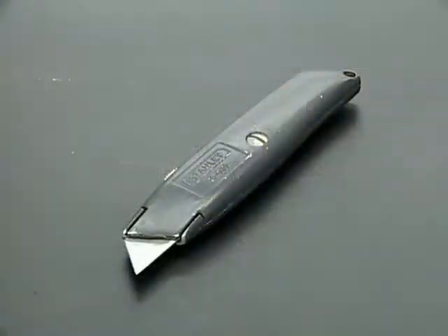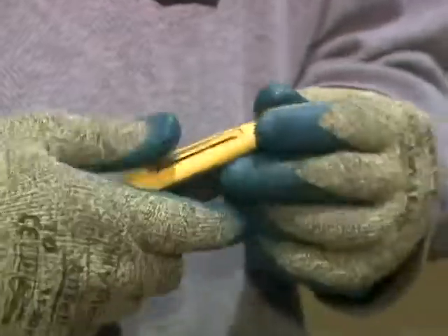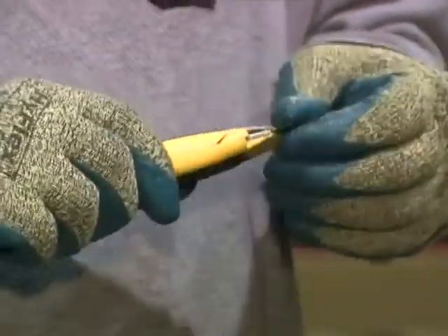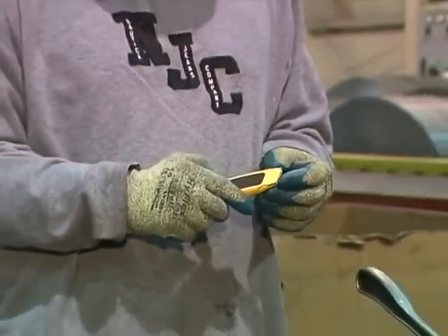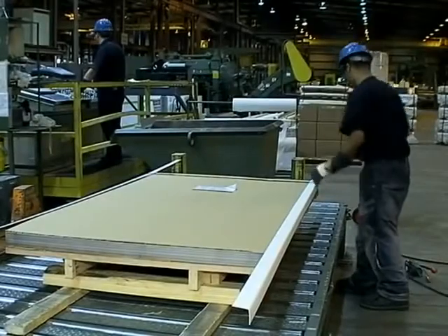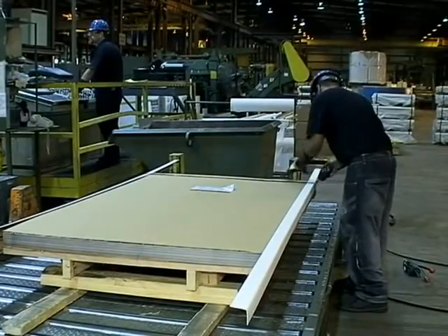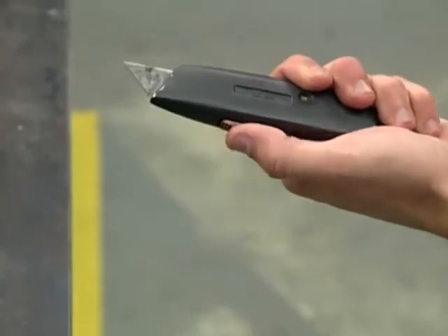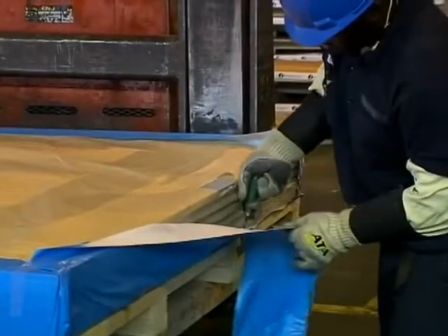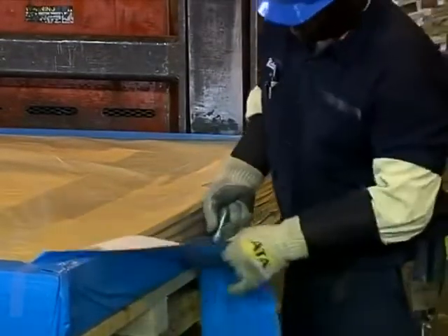Cutting devices, such as utility knives, are common in the work environment. Always try to utilize utility knives with appropriate safety devices that protect the blade or have retractable blades. When using them, be sure not to cut towards your body. Also, ensure that the blade is secured and locked into place to prevent injury. Hold objects in such a way that the tool won't come into contact with your body.